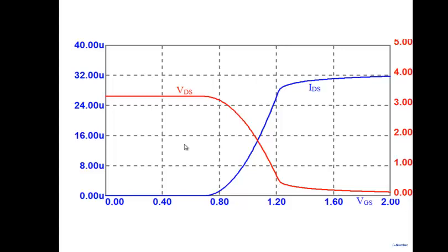So obviously now if you take your MOSFET and you bias it at this region, it's not going to respond, right? There's no change in VDS. Remember, VDS is where you take the output. So there will be no change in output here, and you're not going to get much gain here. Similarly, if you drive it here, again it will not work properly.